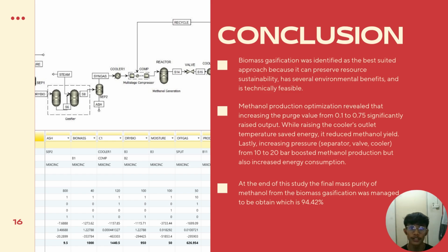The overall process involved multi-stage biomass gasification, which includes pyrolysis, combustion, and gasification zones in the fluidized bed gasifier. The Aspen Plus simulation employed RSTOIC for combustion and RGIBBS for gasification, assuming steady state equilibrium chemical process and isothermal blocks and using the Peng-Robinson equation of state.